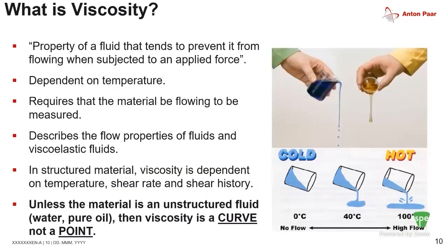Now, getting into what is viscosity. Viscosity is just the tendency to resist flow under applied forces. It's highly temperature dependent, as you can see from the image on the right. The blue ink is very easily flowable because it flows out very easily, whereas the yellow oil in this case has a higher viscosity because it holds itself together better. As I increase temperature, viscosity will decrease as a function of increasing temperature.